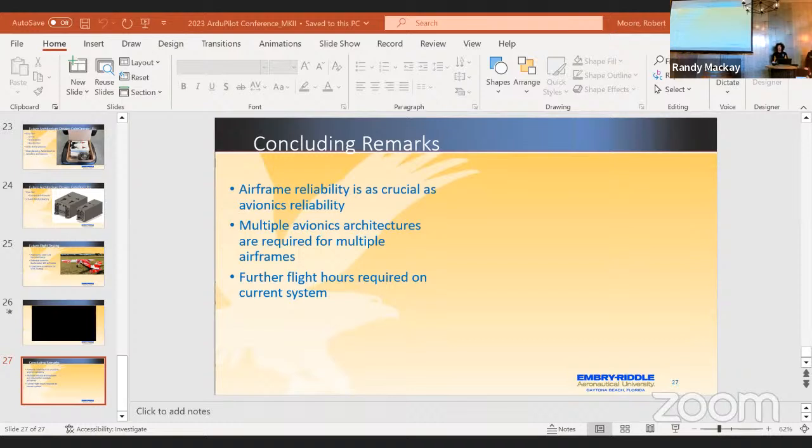Standby mode basically says, we know you're not happy, but we're going to remove your ability to build up those integrators. Otherwise, if we switch to you, you have a huge step.